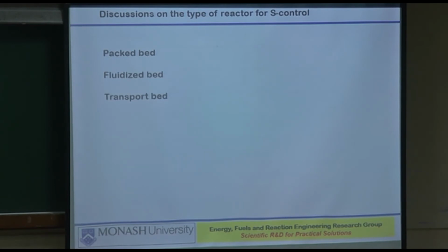So gas volume is fixed by you as the client, and they will tell you that this is the size of the particles. Then you can decide whether you make a tall one with a very small diameter, which will have its own maintenance issues, or have a reasonable size and not so tall ones. Those are the considerations, and you can then decide what you will do.